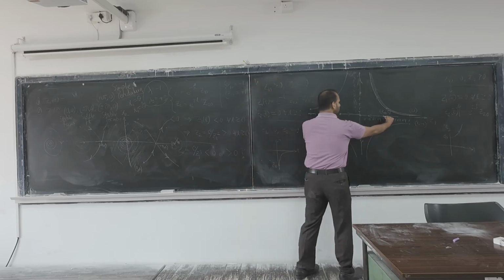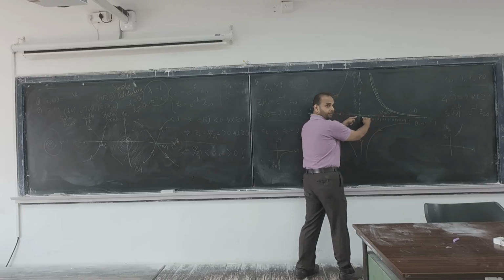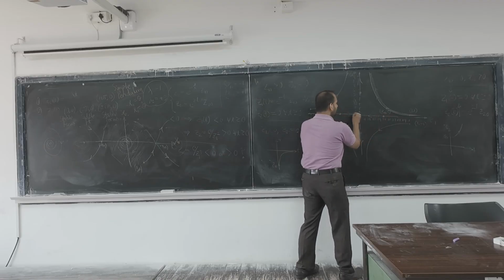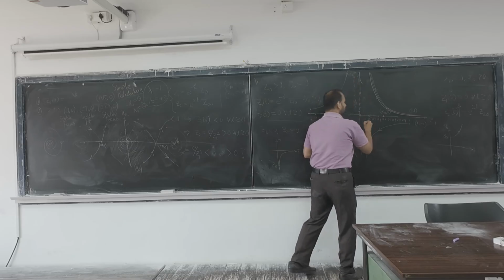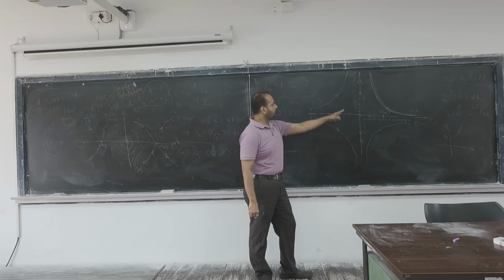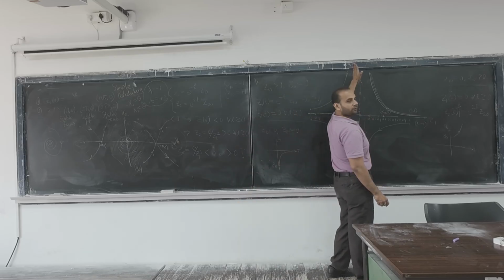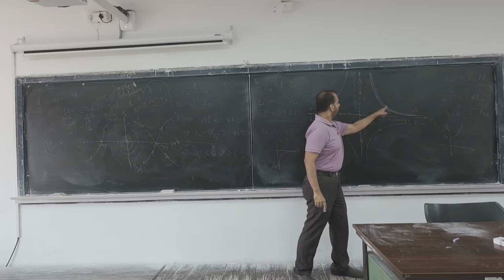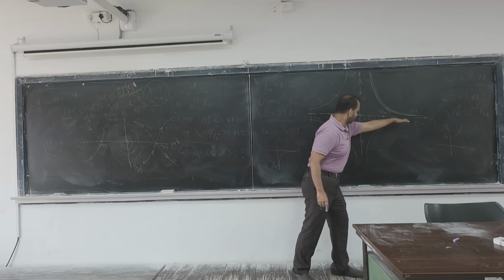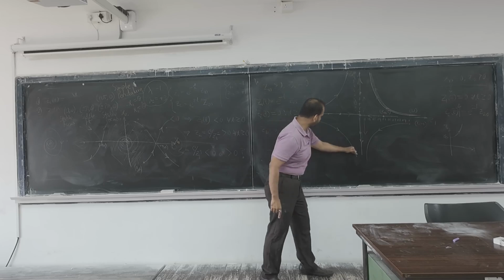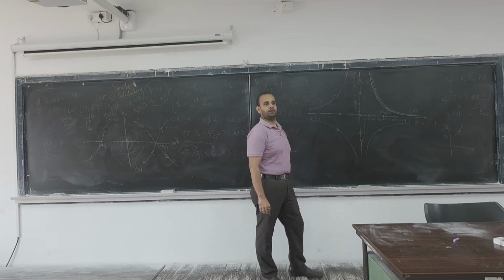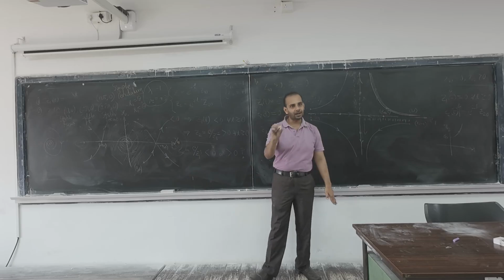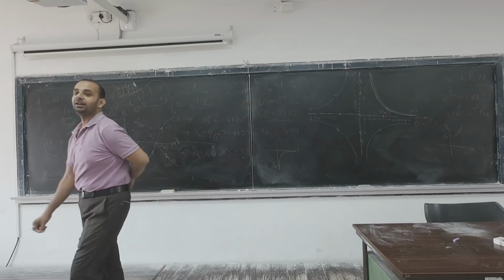Once again, you can see these two are approaching the origin. That means stable nature. But once they reach it, after that they will diverge. One goes this way, another this way. And all the other patterns you see go this way, going upward, right? So in all the directions they follow this; here it is diverging, here also it is diverging along this, along this, along this. So this is called the saddle point equilibrium point, which is unstable in nature.